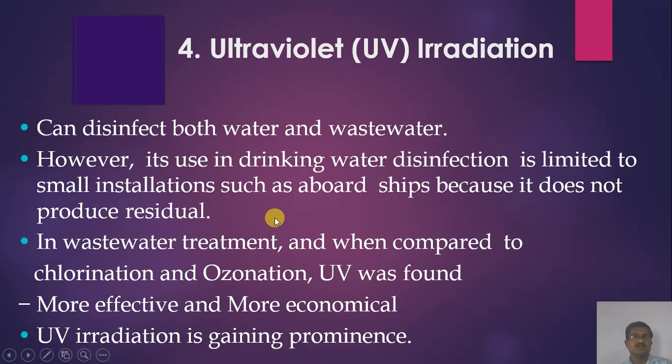Next one is ultraviolet or UV irradiation. It can disinfect both water and wastewater. However, its use in drinking water disinfection is limited to small installations such as aboard ships, because it does not produce residual. In wastewater treatment, when compared to chlorination and ozonation, UV was found more effective and more economical.